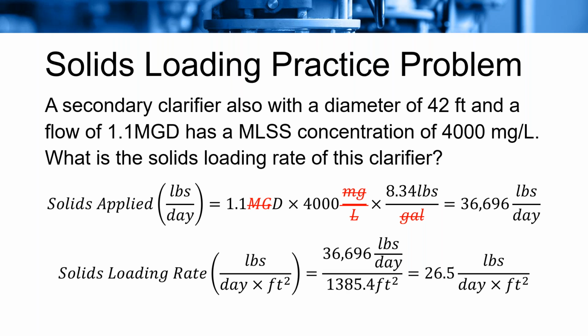Are we getting any stuff on that? Because this should be, if you'll notice, our solids applied is the same as a typical loading. So it's pounds per day, and then you divide that by surface area. So it should be pounds per day per foot squared, because it's based on the surface area of a clarifier.